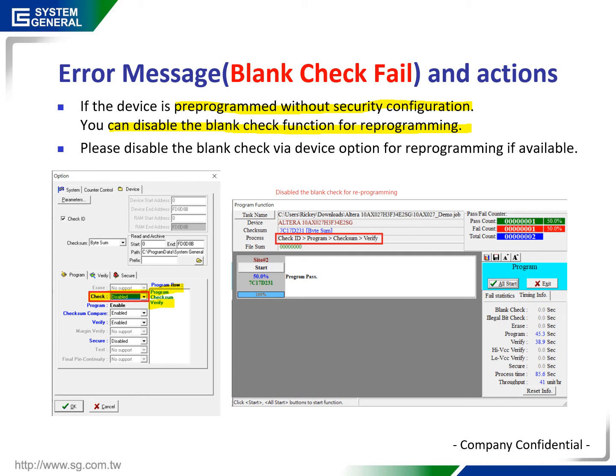Even though the design security key is one-time programmable, the condition is that you need to ensure the previous device has been programmed with the same design security key. Otherwise, we will get the program fail or verify fail.